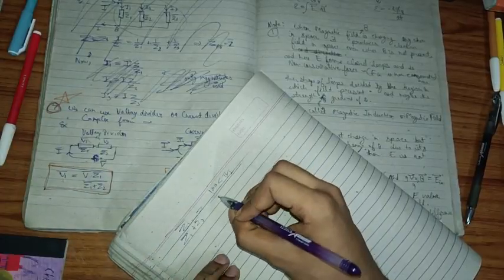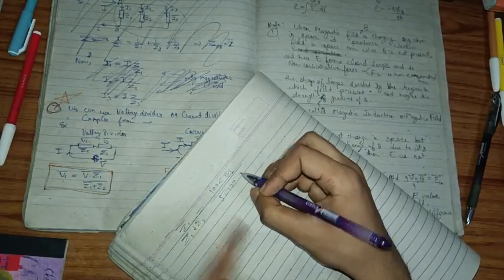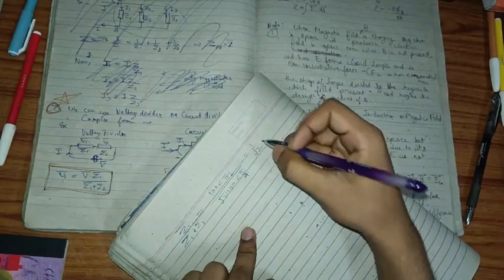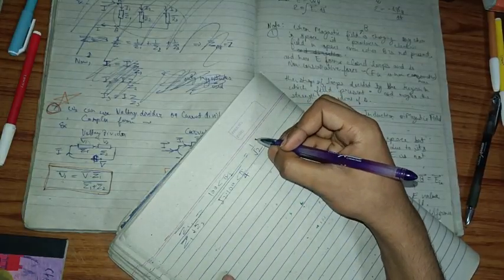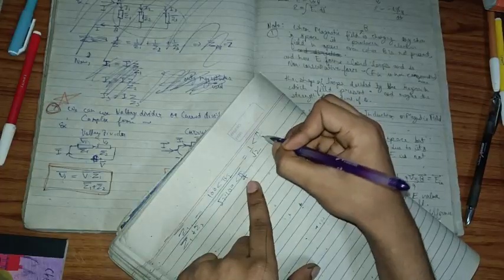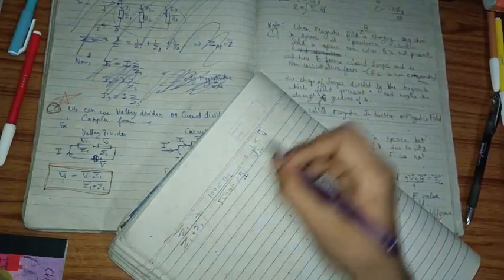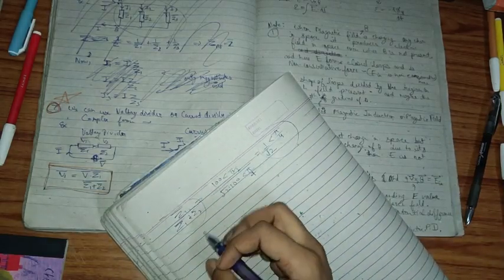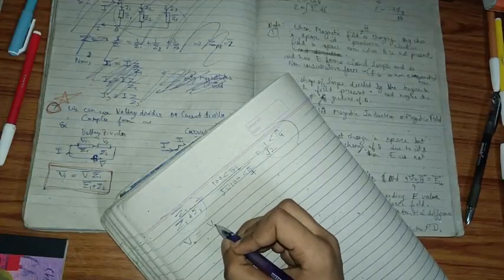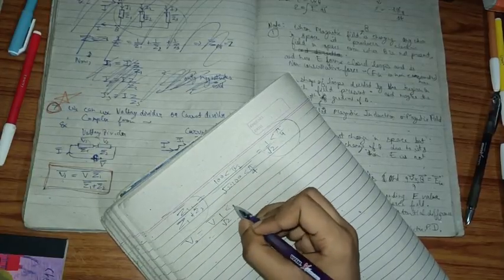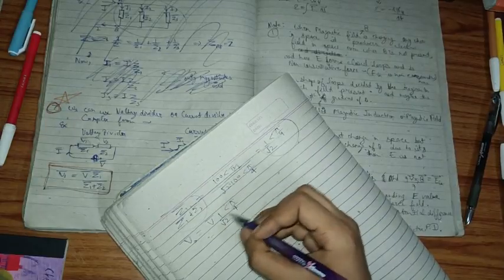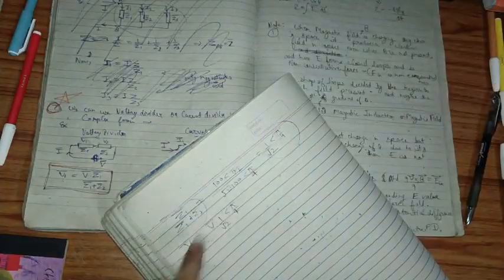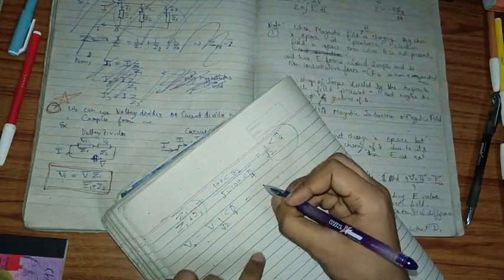In this question, this whole value turns out to be this, and so it means the V O is equal to V into 1 by root 2 and multiplying by this angle pi by 4, and because this angle is actually pi by 4 behind, it means it is having minus pi by 4 angle and we are adding pi by 4 angle to it, so overall angle becomes 0 and we get V by root 2 at 0 angle. This is the magnitude, sorry, this is not V naught, it is V. It is V at 0 angle divided by root 2, and I have removed this bar because now it is a magnitude here only.